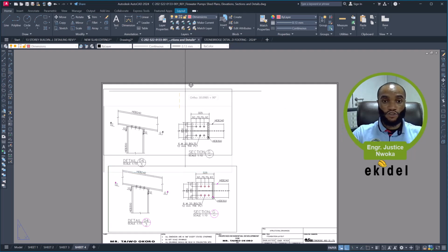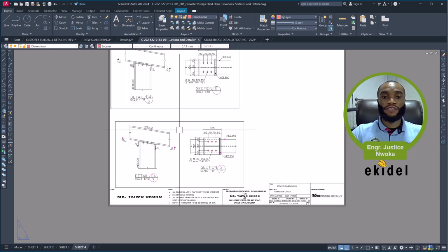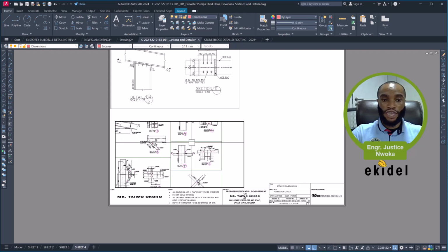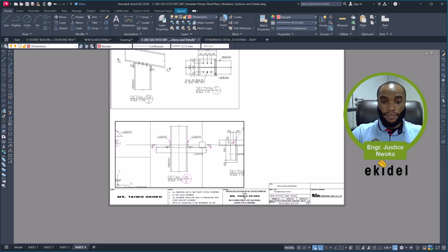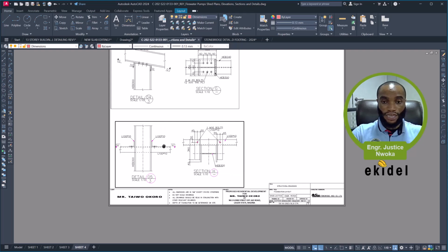And then on this my copied viewport now, I'll double click on that place and bring in the next drawing which I want to bring out, which is this other one here. I'll then type Z, enter, 1 all over 10 SP. 10 there is the scale, enter. And I'll pan again to position the drawings to a particular place here. That's okay.